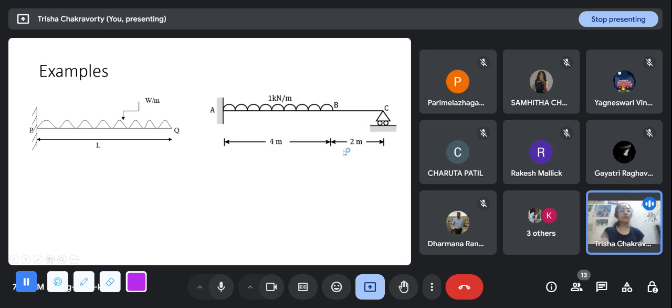Since it was not mentioned, we just look at it and assume it's a beam element, because as you get into this course, looking at this will obviously look like a beam. But do not assume that if it is not mentioned, you have to consider the axial part as well. Now this is a frame, and frames have all three modes.